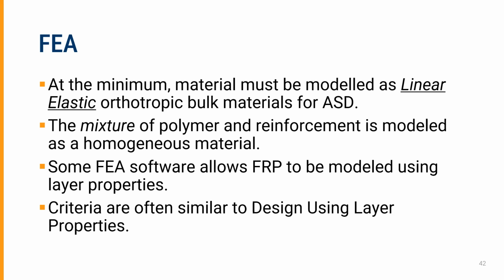And by the way, classical lamination theory, which I talked about, essentially reduces each layer to a homogeneous material. The criteria are often similar to design using layer properties, where we can look at individual layers in those cases and solve for strain in individual layers.